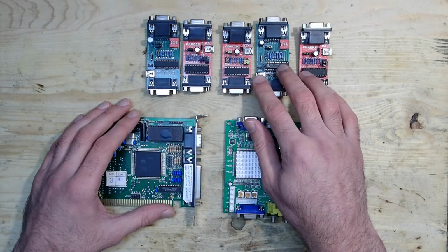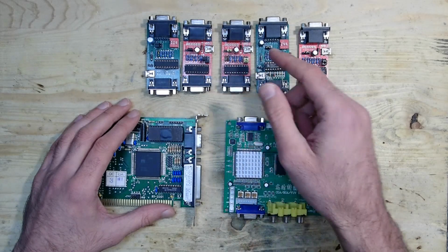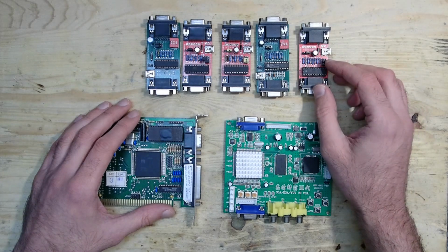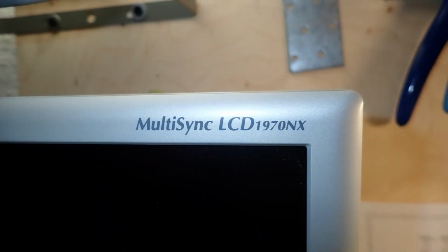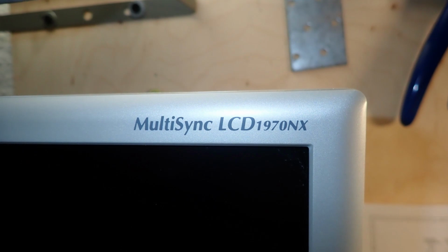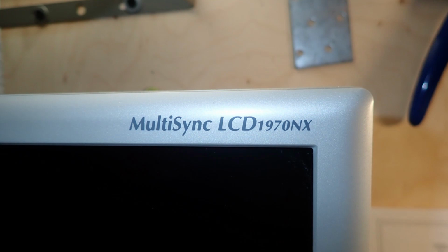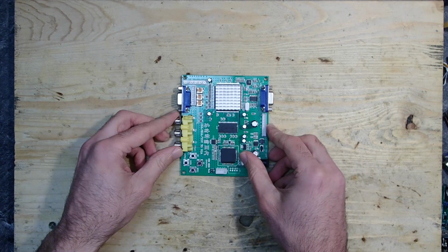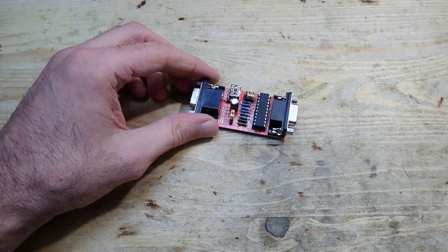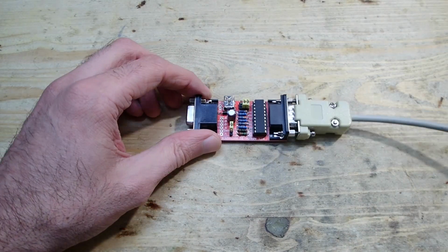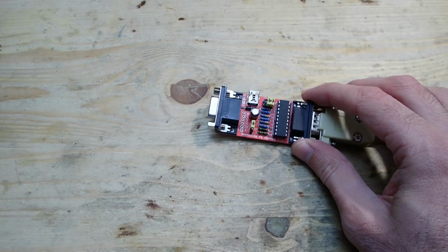During the work on this project, I tested the MCE adapter with some VGA monitors which support frequencies below the standard 31 kHz. Long story short, my new monitor in the workshop is this NEC Multisync LCD 1970NX. This monitor can handle all required frequencies above 15 kHz horizontal and 50 Hz vertical. So I don't need any GBS 8200 anymore. To connect my Hercules, MDA, CGA, low and high-res EGA PCs, I just need my MCE adapter, which I can plug between the graphics card and the monitor.